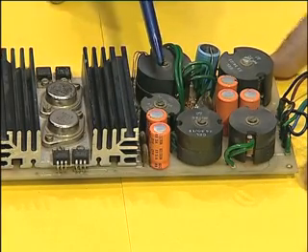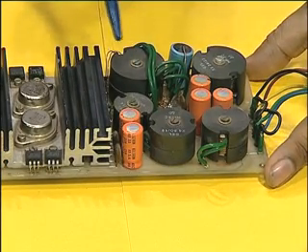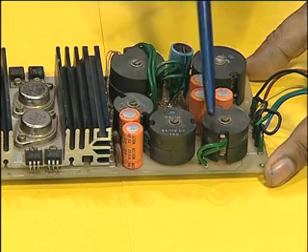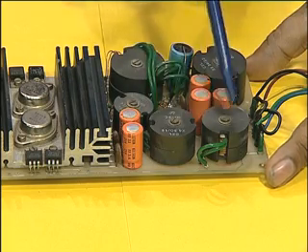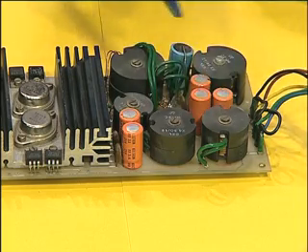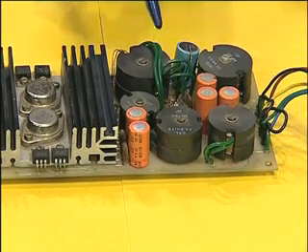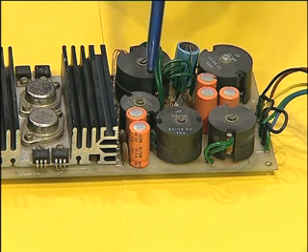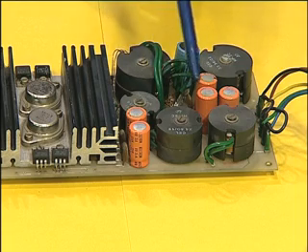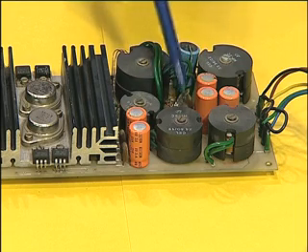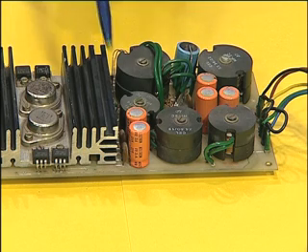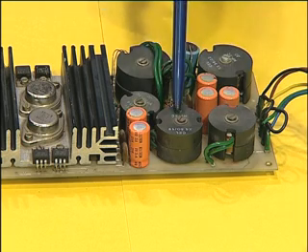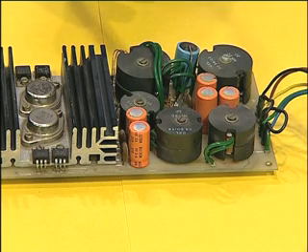and then gradually if I move this board here, what comes into focus are some pot cores. This pot core is used as a transformer. These pot cores are used as inductors. Again, some electrolytic capacitors for the output. The pot cores here are the ferrite pot cores, and they are normally for high frequency applications. They can be used for applications ranging from 20 kilohertz to 100 kilohertz, and special cores even up to 300 kilohertz and further on. If you want to use for low frequency applications like 50 hertz applications, one has to use not this ferrite material, but the silicon steel material.